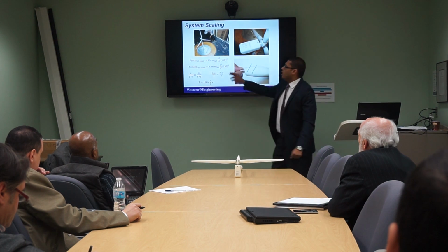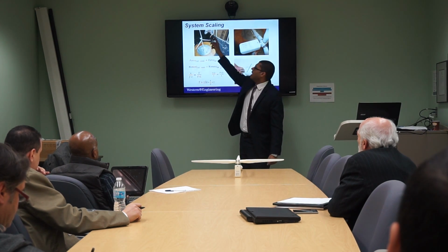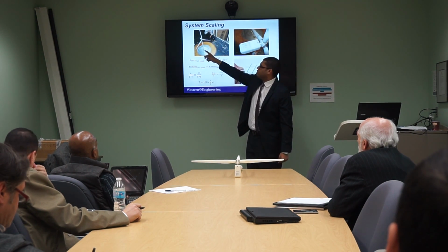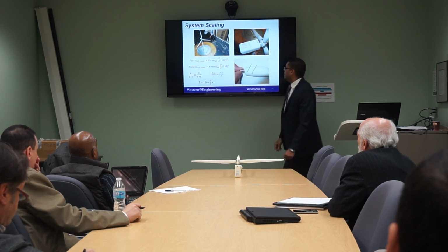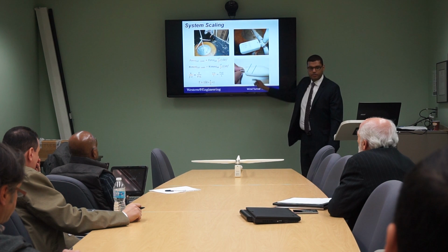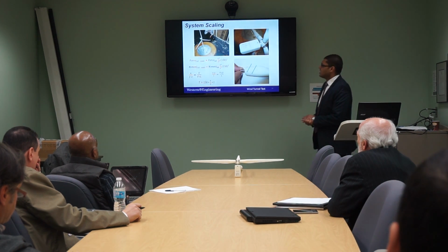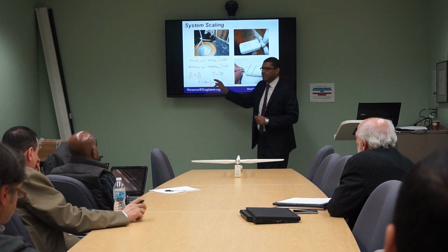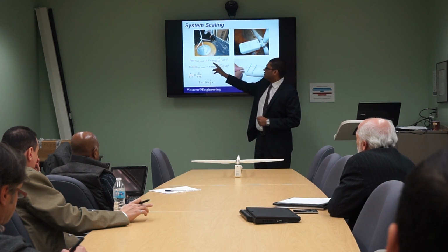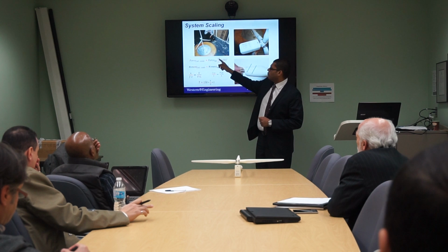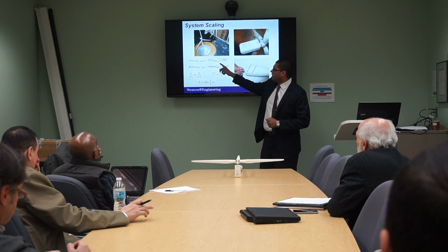Before we start, we have done our calibration for our model by applying known loads to be able to see the load here at scale. And we can see here, this is the angle of the plates. This is the load that we have used for scale down in the wind tunnel test. This is the force in full scale, related to the force in the lab, related to the actual wind speed and the wind speed in the lab.